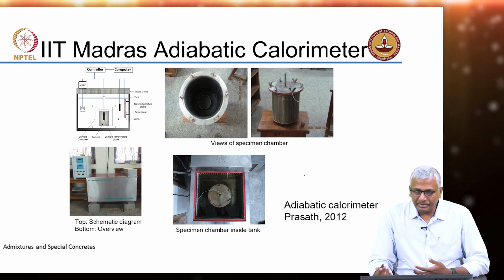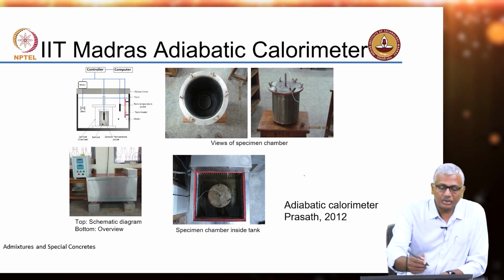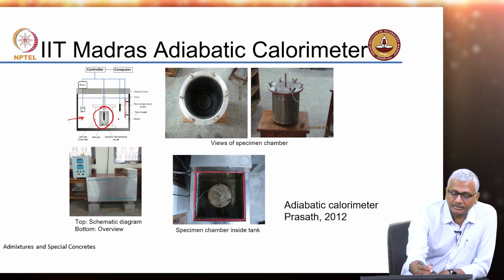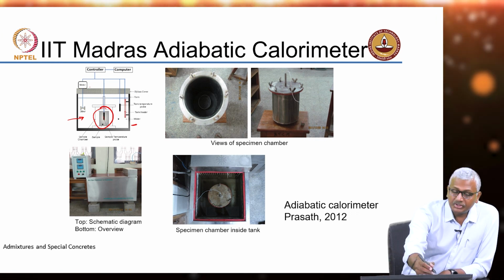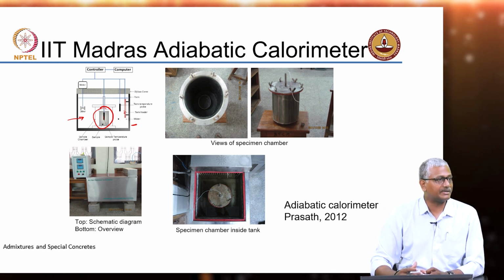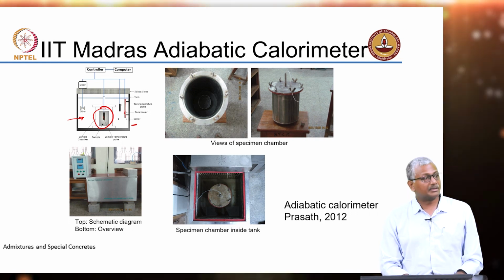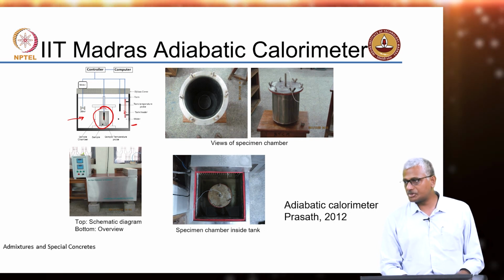So, in IIT Madras we have been using the adiabatic calorimetry tool. Here, as I said, you have the sample inside a chamber, and this chamber itself is enclosed in a water bath. This is a water bath, and the water bath has a heater. The temperature of the concrete is measured with the help of a temperature probe and fed into a controller, which then kicks on the heater inside the system to heat the water bath at the same rate as the sample temperature. That way there is no exchange between the sample and the surroundings, and all you keep doing is measuring the increase in sample temperature.